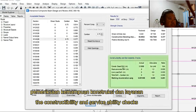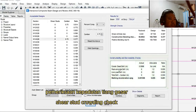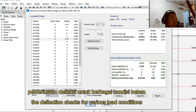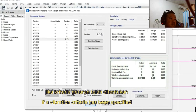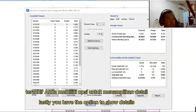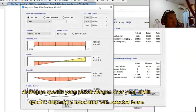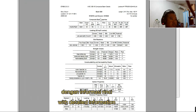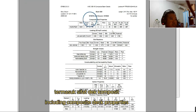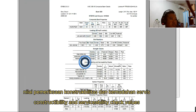The constructability and serviceability checks likewise display the details of several types of checks: shear stud crowding check, the deflection checks for various load conditions, one or more vibration checks if a vibration criteria has been specified. Lastly, you have the option to show details to take a look at specific diaphragms associated with the selected beam, or you can take a look at a report for each specific beam with detailed information, including composite deck properties, governing load combination and reactions, and all the strength check, constructability, and serviceability check values.